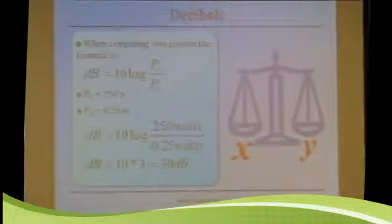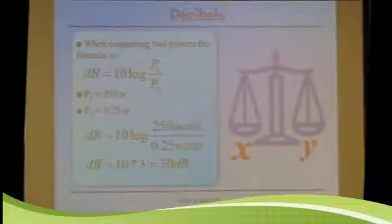And the general thing to remember, decibels are logarithmic powers. And so in reality, 3 dB is the doubling of power. So if you double your power, you've got a 3 dB gain. 6 dB is quadrupling of the power. 10 dB is a 10 times change in power. And if you're decreasing the power, or you're losing signal, then halving the power is minus 3 dB. 0 dB is no gain or loss.